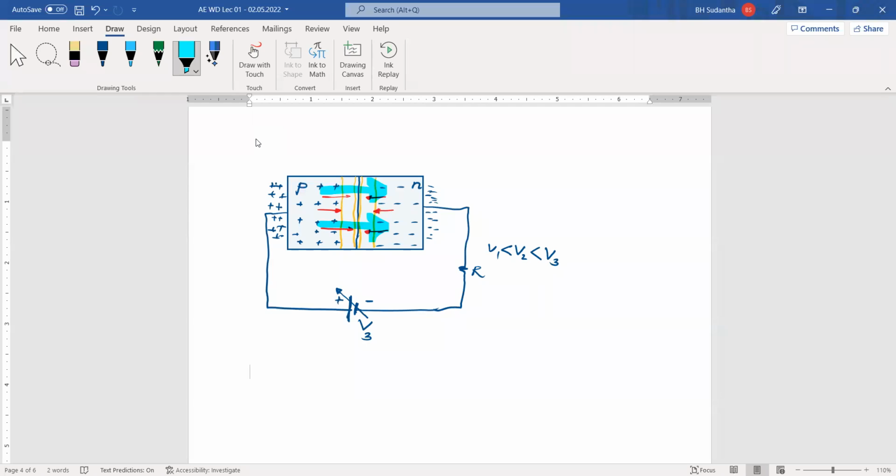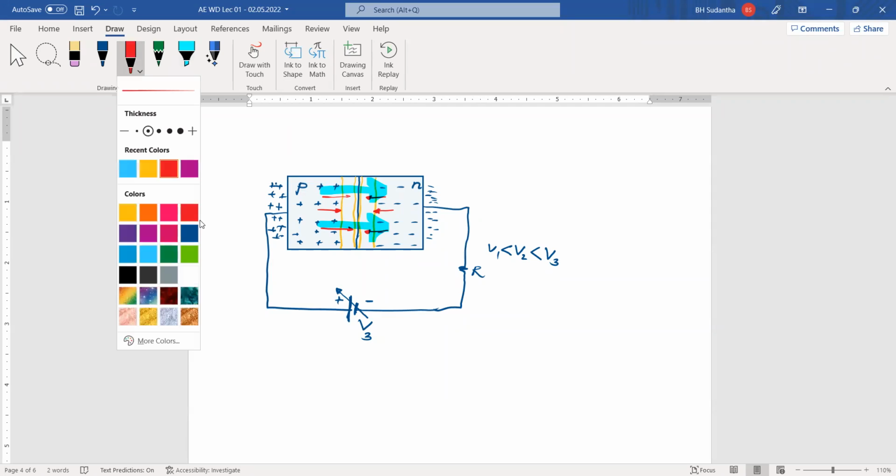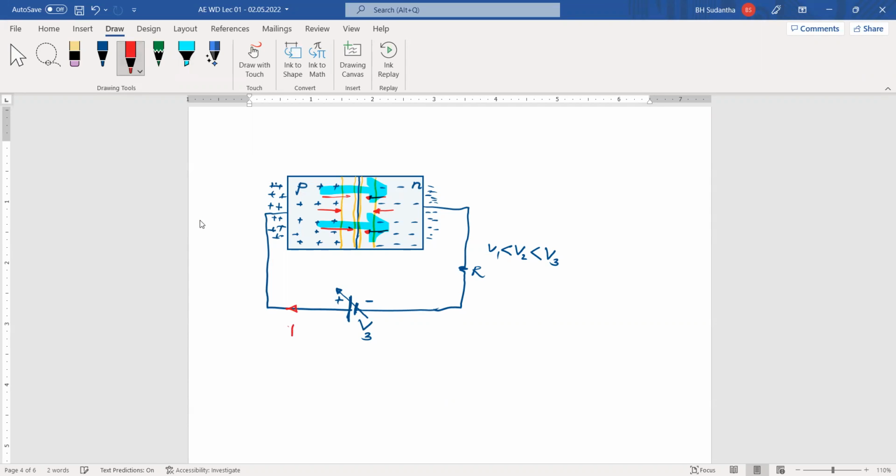Then as a result, what can you observe in the external circuit? You can observe here that current is generated. Why? These charges are going from here to here. And these negative charges can come here, these positive charges can come here, and they will destroy this depletion layer, and then across the border, the charges can travel. Okay.